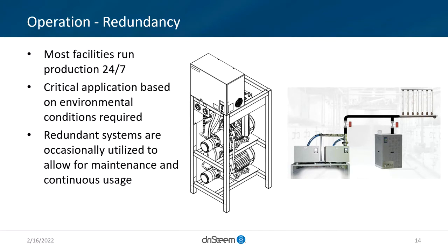Well, some of those answers are redundant systems, depending on system type, N+1, 2N, 2 (N+1). Looking at those different control schemes, it's product dependent, depending on which control scheme you want to do. But there are options here at Dry Steam where we can really tailor that to your need.